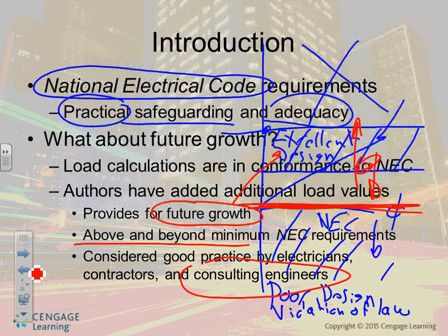Okay, that's another idea that a lot of engineers use, which is a good idea. Now some contractors might push 12. Now you want to say no more than 6 circuits in a 3/4 of an inch. That's your engineering specification, so you don't want to push more than that. So anyways, that's kind of where we're going above and beyond code, guys, and planning for the future.